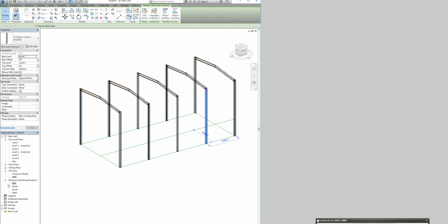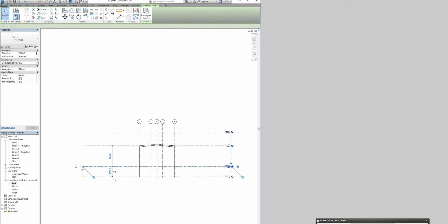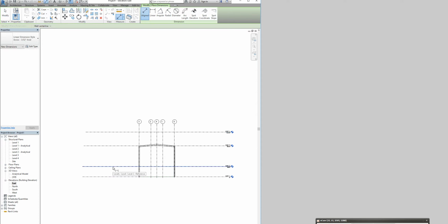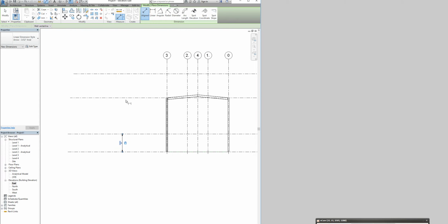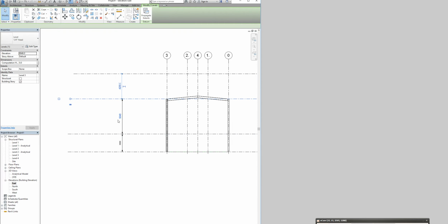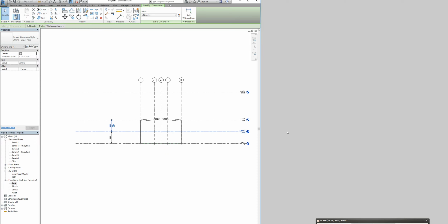Alright, so now it says set elevation distances as 3000, so we set this as 3000. I showed the guys in architecture, in the architecture class, the first class, how to lock these distances. So we're just gonna lock it, just basically go to this measure and lock this elevation here, and same here. I got 6000. I'm gonna change this to be 3000, and I'm gonna lock this here. If I want to unlock, it's just click on the lock here. They already know how to do this. I showed them in the first class, so that's why it's not detailed in the slides.